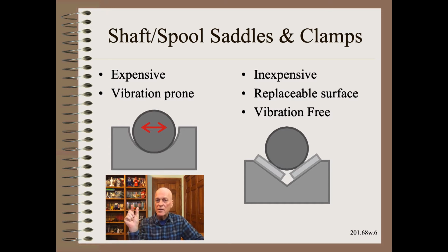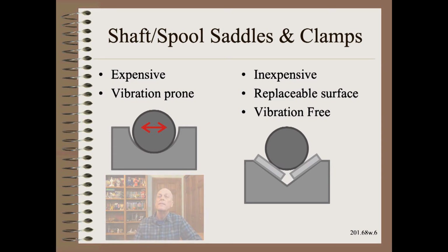Any clearance or play in the mechanical system can allow for pounding vibrations. It is challenging to reduce the clearance of chucks and shaft holders by some combination of design and maintenance. Often, especially for high-speed machines, this clearance may need to be held to less than the thickness of a human hair. Some designs are far better than others in this regard, but that is beyond the scope of this clip.